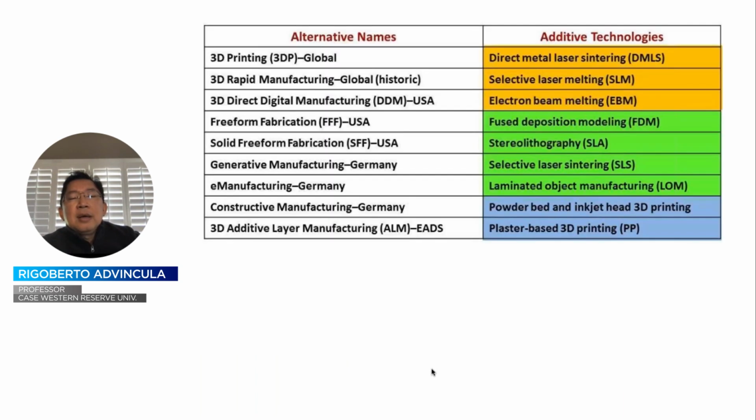So let me start then by reviewing a number of methods that are popular, including FDM, fused deposition modeling, and stereolithographic apparatus, which we will focus on today. That includes digital light processing, or DLP. And along with these two methods, the other important methods include binder jet, powder fusion, SLS, DMLS, and other types of manufacturing methods or 3D printing that extends to metals and ceramics.